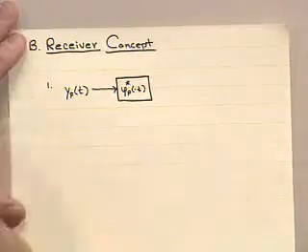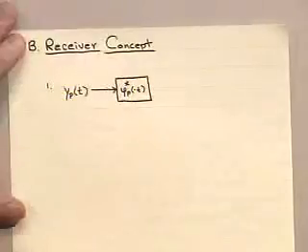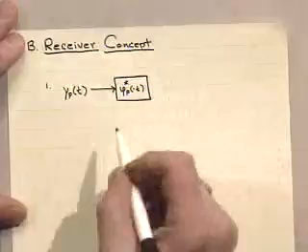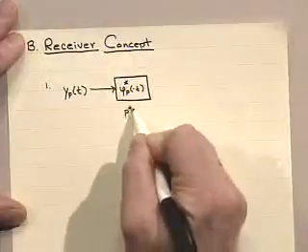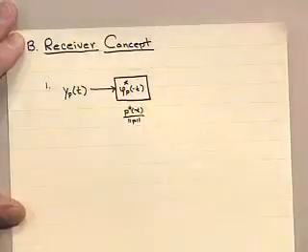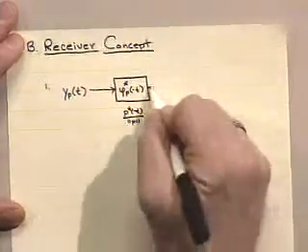So integrate the squared energy in a function, you get some number for that, and then divide by the square root of that, and that's the norm for the system. So this would be p star of minus t over norm p, which we could compute if we know the pulse response, we know the channel. We would be able to do that.